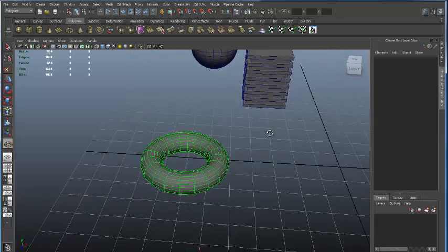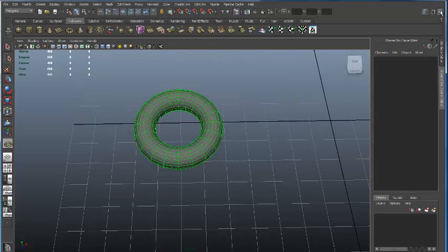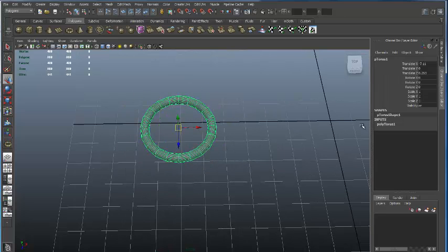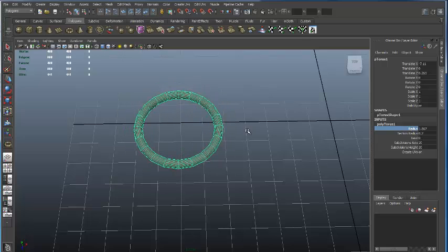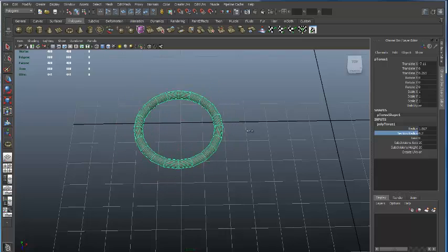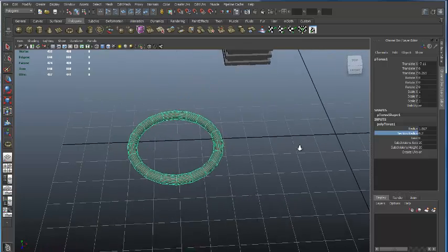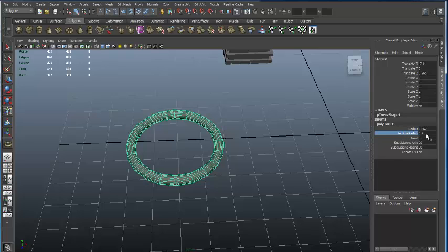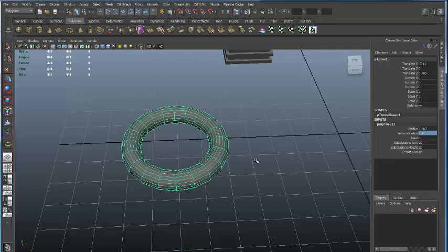That's a little thick right now for a pipe for me, and there's some jagged edges on that. So I'm going to select that object, go into the input selection here. I'm going to come down into the radius, I'm sorry, section radius. I'm going to scale this down and get a little bit more of a hose consistency. Now it's a little bit harder when I touch on it and do the middle mouse drag. I might need to actually come in here and enter a couple numbers like 4 if I want to make it a little bit thicker.